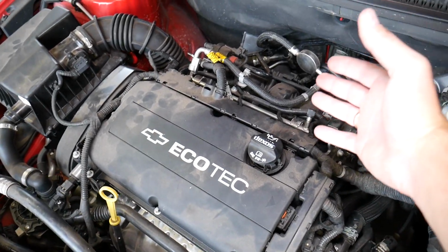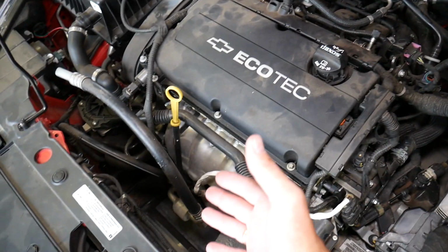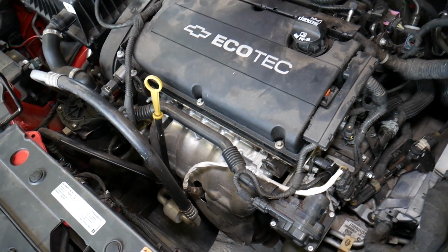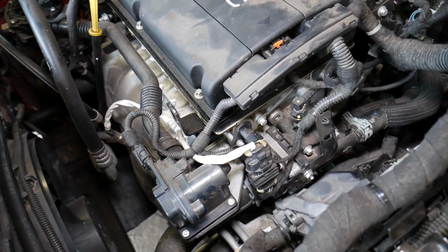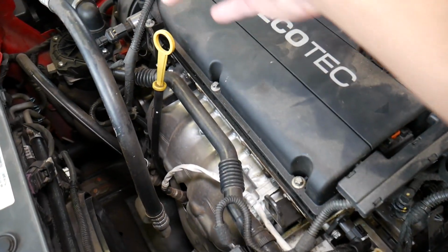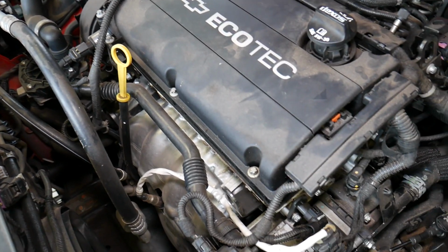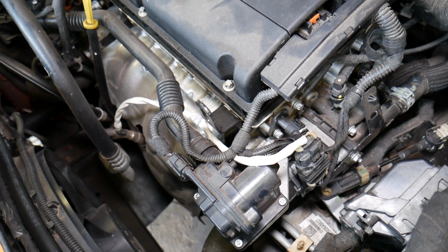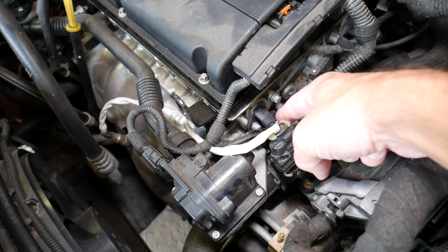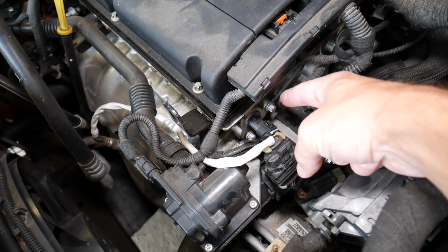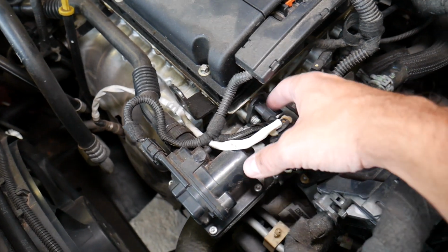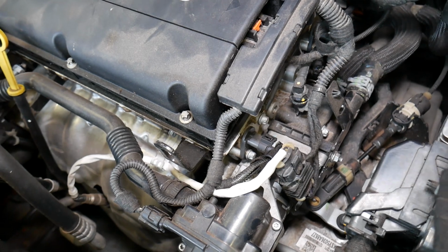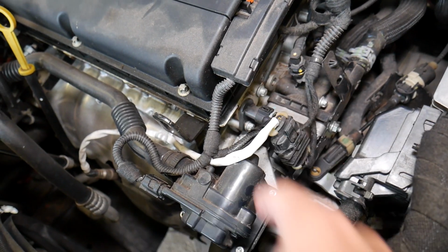Because the engine first gets fuel and air, and then the gas comes out of the engine through the exhaust. So this is the side for the exhaust camshaft, and the sensor that we're looking at now is camshaft position sensor B, that little sensor right here. So check your connector, check your wiring harness, make sure it's not loose. Now if that doesn't fix the problem, you will need to go ahead, remove the sensor and replace it.